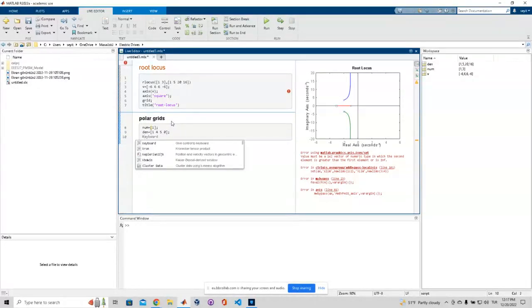So now you are going to define your k variable, which is, let's define with 0, 0, 1. So now we're going to define R with capital. And then we're going to take root locus. For taking the root locus, inside you need to define your system again, your numerator and denominator, and with your variable k.